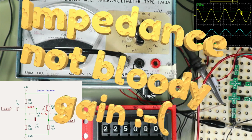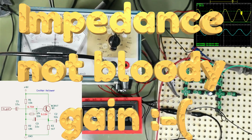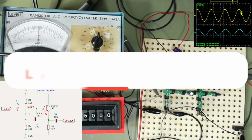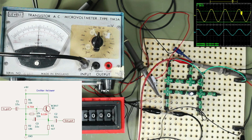But it just goes to show that putting the bootstrapping in the correct position, i.e. the output back to the bias chain to effectively remove the bias impedance from the calculations, does what we expected. And putting the bootstrap capacitor, or so-called bootstrap capacitor, across that first example of the collector load did nothing.